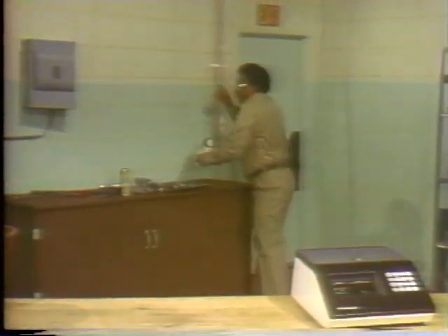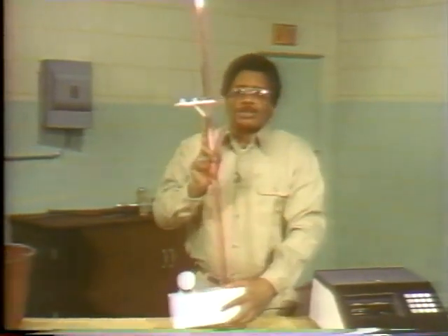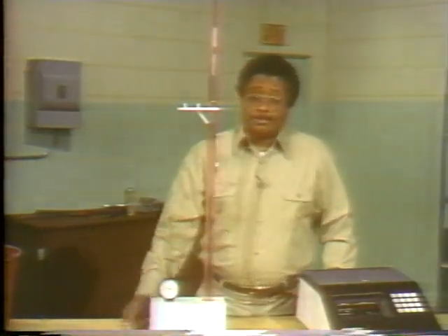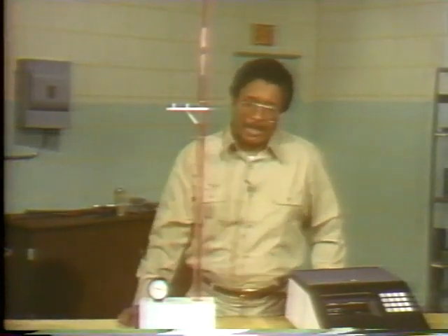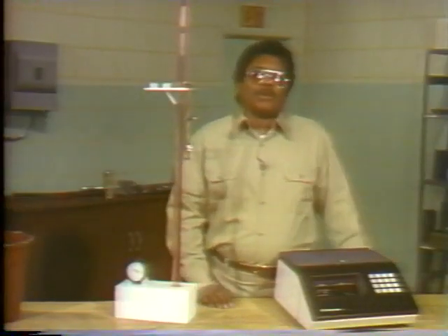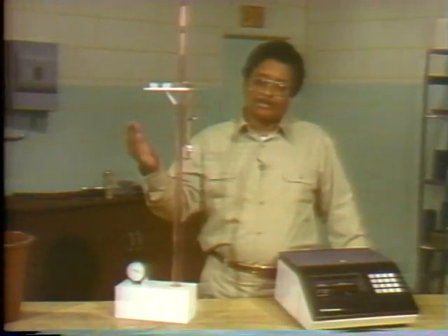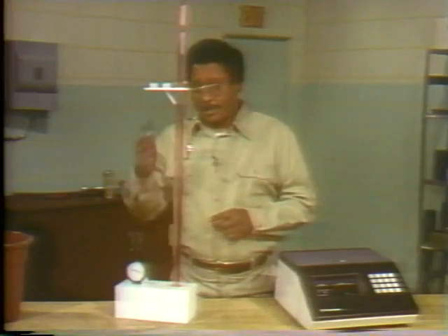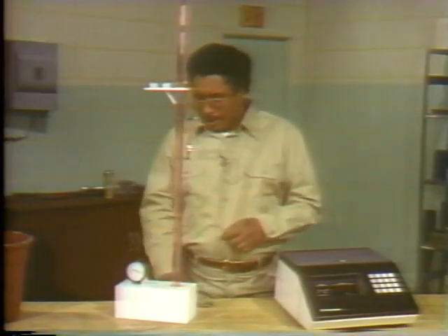Now, here's a column of water that's 5 feet in height. We know from what we've done so far that the pressure of a 1 foot column of water is 0.43 psi. So, a 5 foot column exerts 5 times that, or approximately 2.2 psi. The gauge connected to the bottom of this column shows this is true. Now, what about the pressure 2 feet from the bottom? What should it be? Well, I'm moving this gauge to a place 2 feet from the bottom. Let's see if we can figure this out.